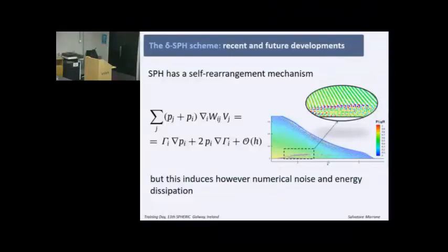And this is also the reason why we use background pressure, because background pressure works with this coefficient, that multiplies the gradient of gamma, which allows filling all the different voids, all the different irregularities. And this is already present in all the schemes that have this shape of the gradient of the pressure.